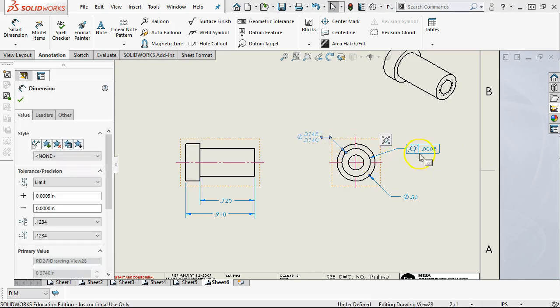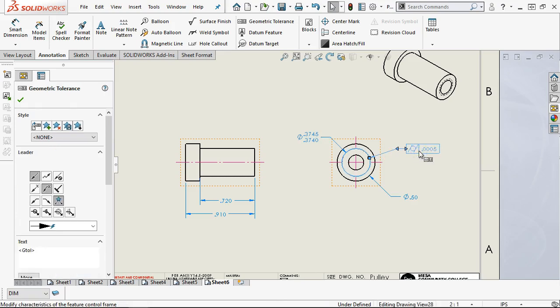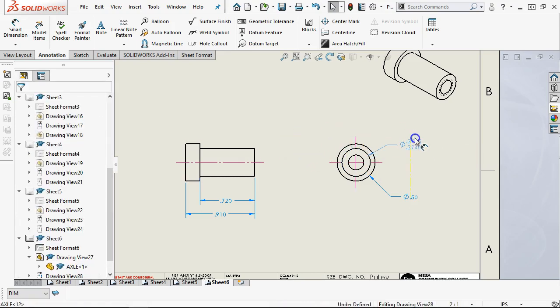Yeah, I'm starting to have a little heartache about cylindricity. I think for the length of 720, I'm going to be able to hold this number cylindrical down the length of it, and I don't know that I need the GD&T. All right, so I'm going to go ahead and pull that one out. I'm going to stay with the numbers, and at this point, all we can do is make it and see what comes out. All right, so this number being that tight, I'm counting on it to control the center line and the ability of this to move more than a half a thousandth.